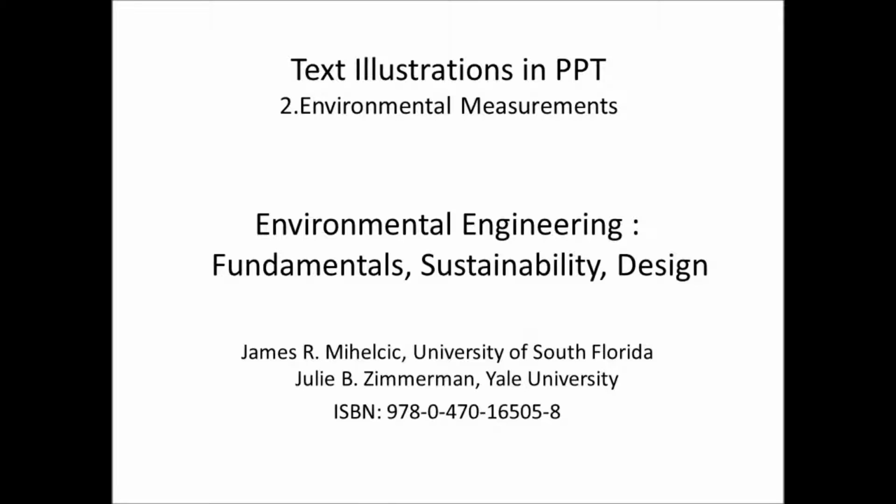2.2, Volume to volume and mole to mole units. Units of volume fraction or mole fraction are frequently used for gas concentrations. The most common volume fraction units are parts per million by volume, referred to as ppm sub v, defined as in equation 2.5, ppm sub v equals V sub i over V total times 10 to the 6th, where V sub i over V total is the volume fraction, and 10 to the 6th is a conversion factor with units of 10 to the 6th parts per million per volume fraction.